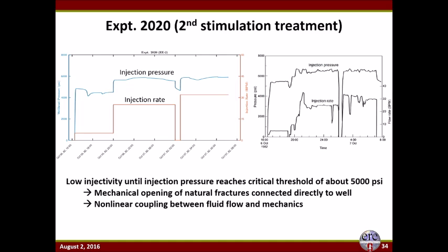In terms of the rate and pressure response at the wells, we observed relatively good both quantitative and qualitative results. One of the most important parts that I want to draw your attention to again is we were able to capture that low injectivity followed by a marked increase at a very specific threshold pressure. And in the model, that was entirely related to the ability for the natural fractures that intersected the well to open as fluid pressure reached their normal stress. So it's really that nonlinear coupling.